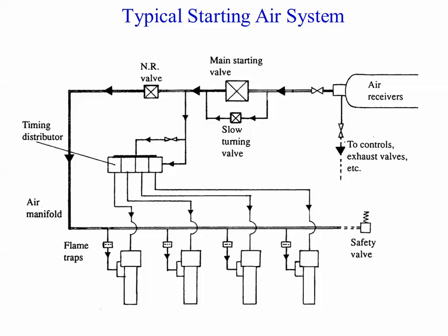On the Bear, we actually have burst discs. In other words, if there was a combustion and overpressurization, the bursting disc would open up, would blow out, and dissipate the energy into the engine room instead of damaging the system. And then you would have to replace the bursting disc afterwards.